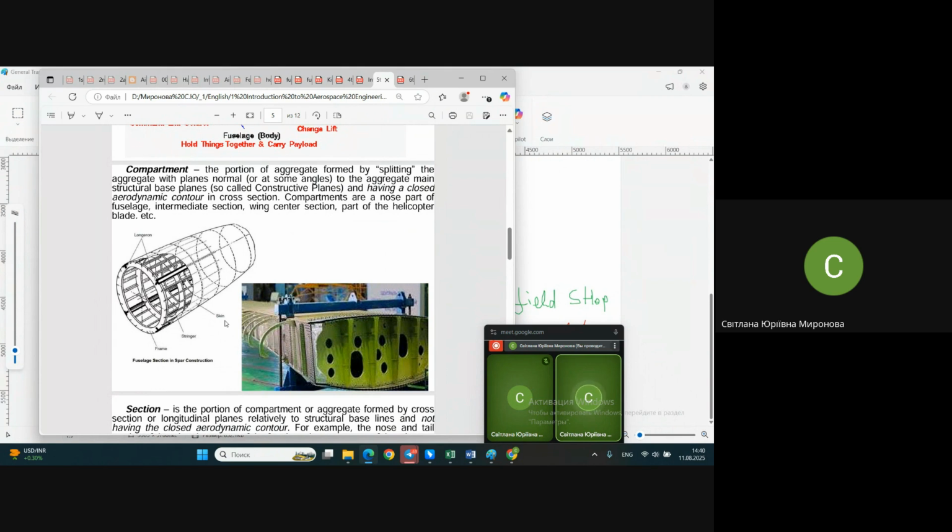So when it comes to serial manufacturing, in terms that the program will be counted in tens and hundreds, in this case, of course, there will be a long preparation and differentiation of assembly work, compulsory, into aggregate, compartment, section, and so on. In case you need to produce only one airplane or a couple of airplanes, like experimental planes, for instance, more probably it will be 5, 7 assembly stations for different aggregates and next final assembly.